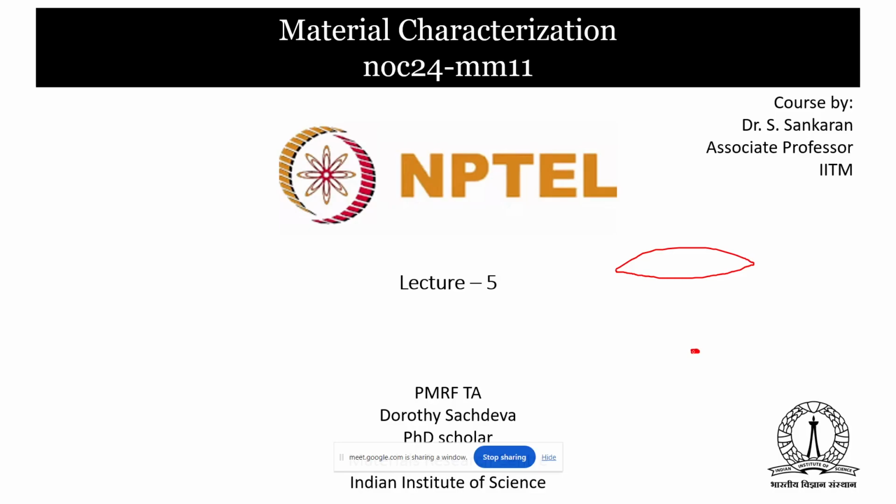But electromagnetic lenses are very advantageous, where just by changing the current passing through the coils, the focal length changes. These lenses are made up of copper coils surrounding the lens. When the electron beam falls, we can change the value of the current passing through these coils, so the focal length will change, and the beam can focus here or here, depending upon the current passing through the copper coils surrounding these electromagnetic lenses.